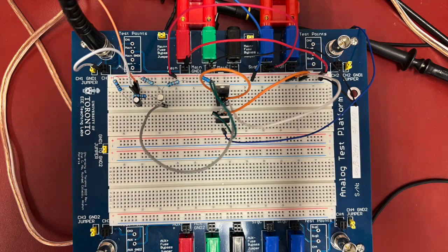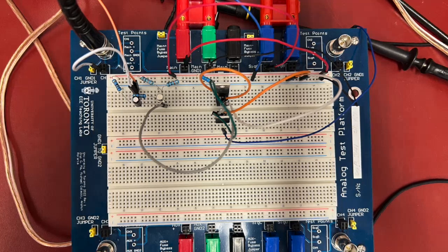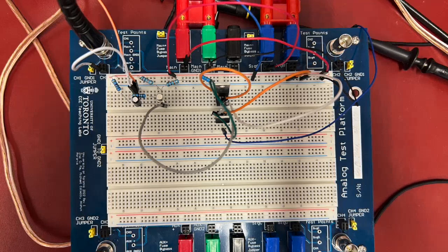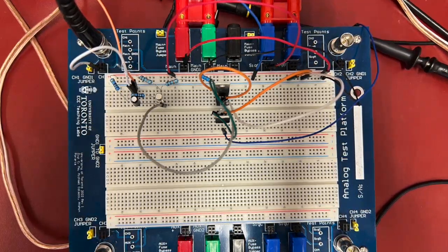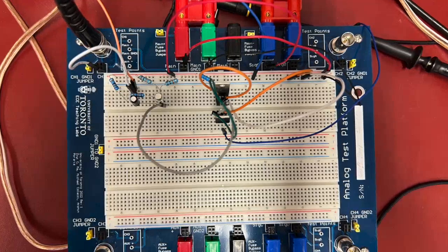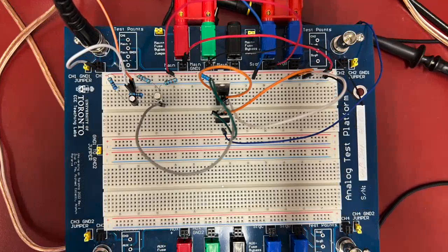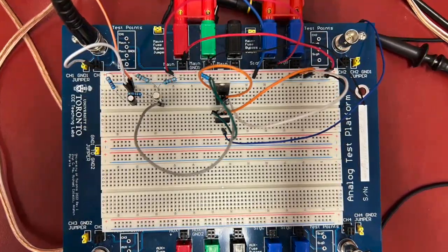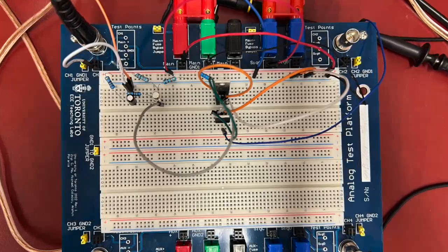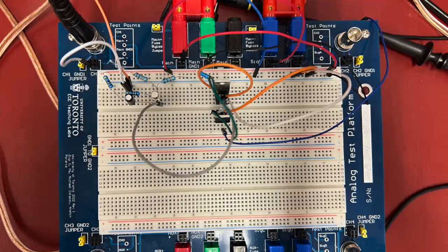For the last part of this lab, we are going to replace the emitter resistor of the common emitter amplifier with a current mirror. Then we are going to deal with this amplifier in two different modes. One is common collector mode, where the amplifier works as a buffer, and we should expect a gain of around 1 out of it.